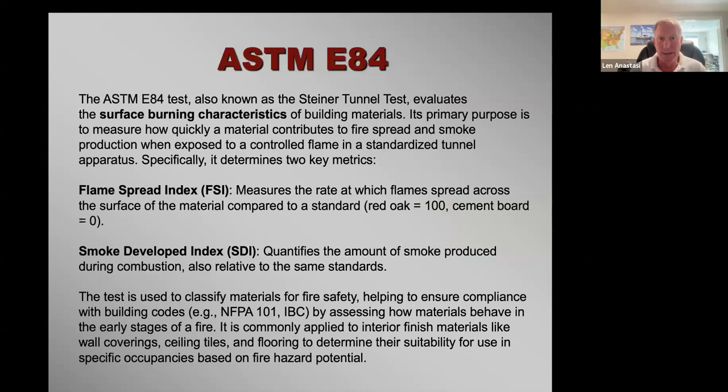So the other thing that I see many manufacturers point to is the ASTM E84 test. They say, "Oh, we passed it." Well, this is not a pass/fail. This is a characterization test. I've spent over 20 years on ASTM. We used to call it the tunnel burn. It's known as the Steiner tunnel test. And what it does is evaluate the surface burning characteristics of building materials. It was written with the intent to assess the burning characteristics of common interior finish materials like wall coverings, ceiling tiles, flooring, to determine their suitability for use in specific occupancies.